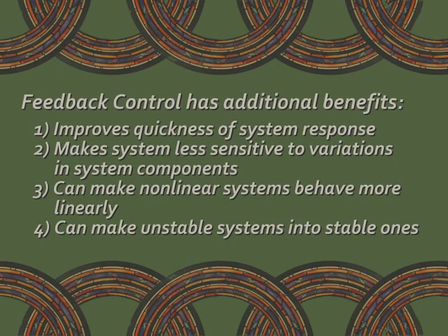Second, feedback control makes a system less sensitive to variations in the system's components. Third, feedback control allows a system to behave more linearly when there are nonlinear components within it. And finally, feedback control can make unstable systems into stable ones. This benefit cannot be achieved by open loop control.